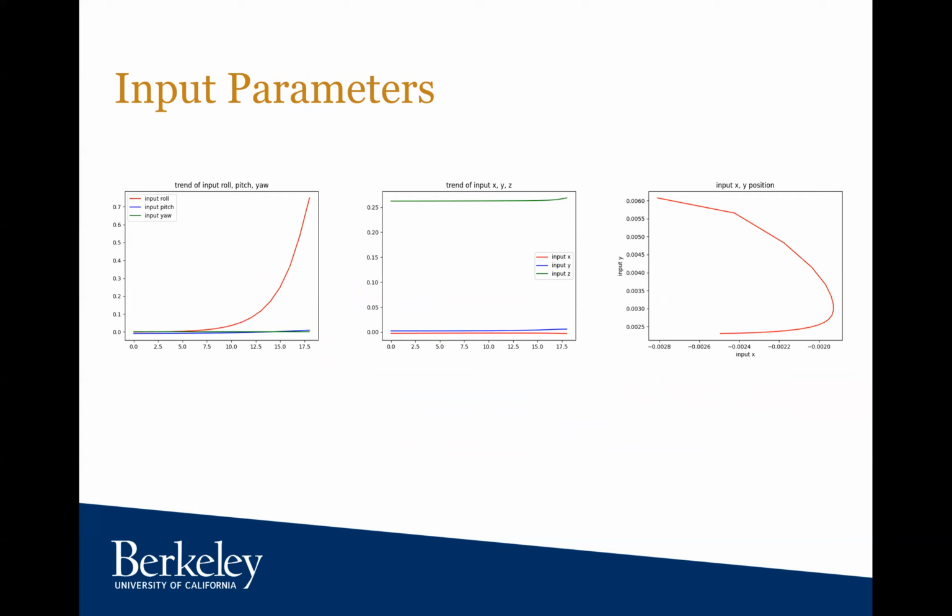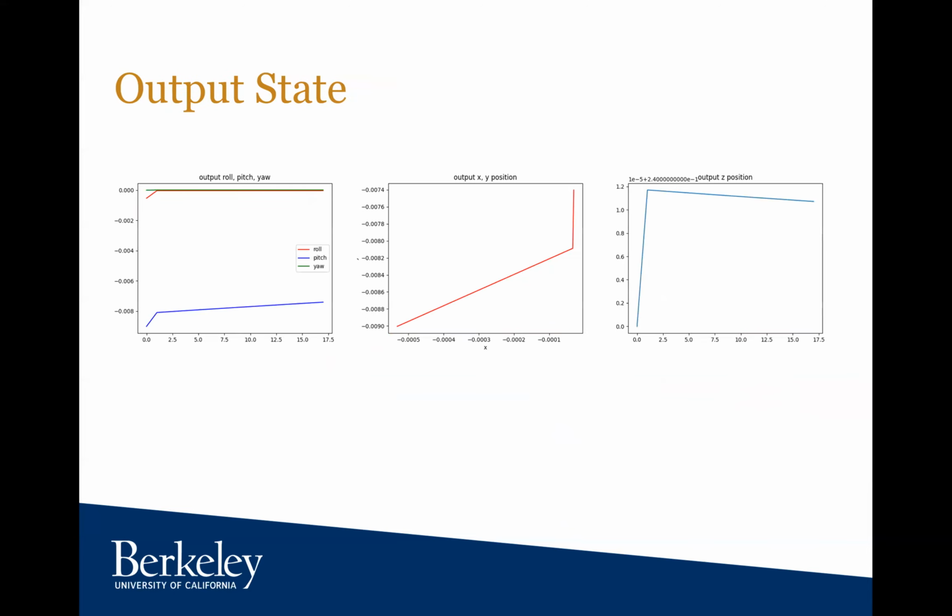The objective of these experiments is to test whether our MPC can stabilize the robot under some disturbance. As shown in figure 1, we intentionally let the roll of the COM increase with time, and in figure 3, we add some disturbance in the input XY position of the COM. As shown in the following figures, our MPC shows excellent resistance to disturbances.